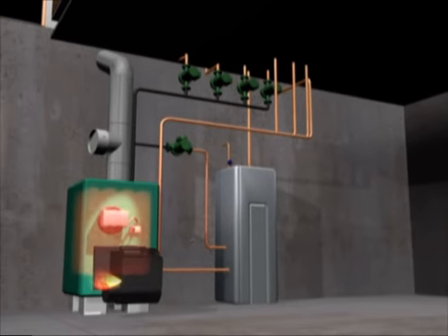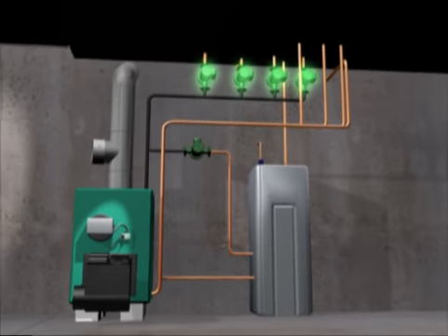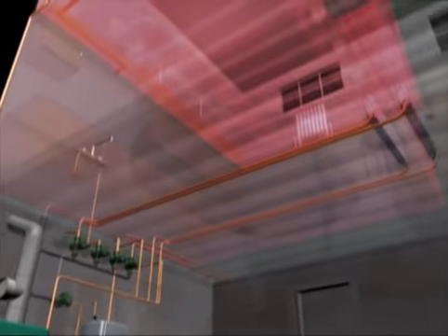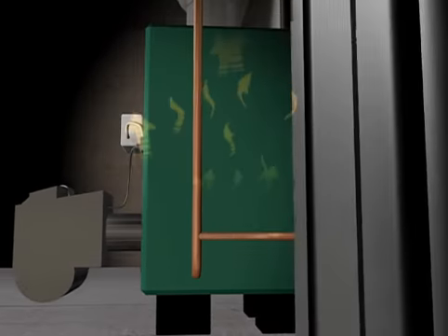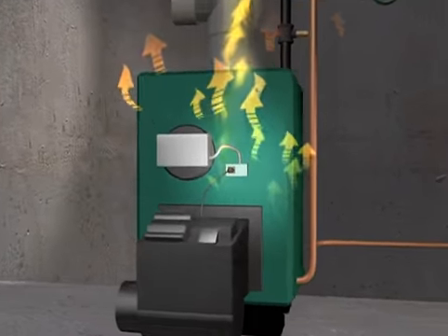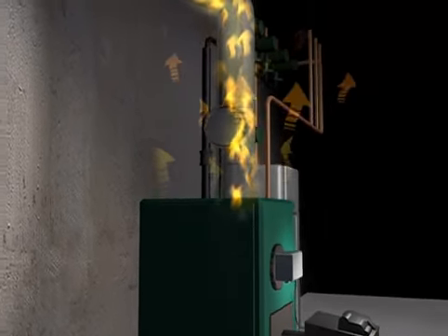Traditional hot water heating systems operate at high temperature all the time and regulate BTU input by starting and stopping circulator pumps and/or opening and closing zone valves. But this on-off method has some inherent disadvantages. Higher operating temperatures lead to more jacket, standby, and distribution heat loss, resulting in lower efficiency and higher fuel consumption.